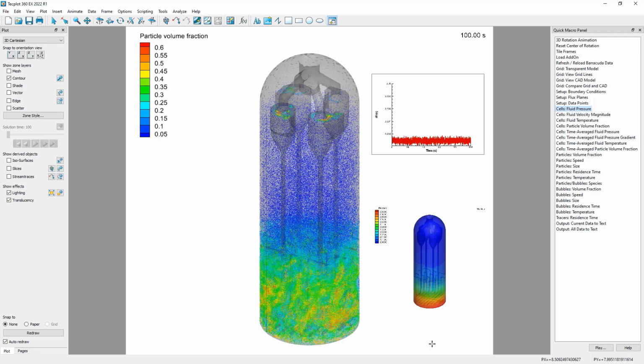However, if we wish to show all 3D data from the same simulation, this is not the most efficient way to do that. Tecplot loads all data being presented into active memory. So with the two 3D sets being shown here, we are doubling the memory load of Tecplot. There's a simpler and easier way of doing this that is also less of a memory constraint, and I'll show you how to do that now.